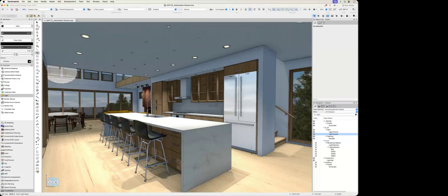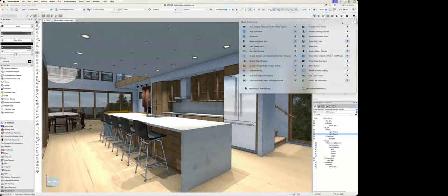So how do we place lights? How do we deal with lights? How do we edit lights? And so on. There is a quick preference setting that is very useful for lights. It's at the top right hand over here, and it says display light objects. If it's not shown on your screen, you could also invoke it over here and look for the display light objects as well. I pinned it to the top, that's why it shows up over there already. So here it says display light objects, and then you click this and it says only in wireframe, always, or never. So I like to keep it in wireframe.